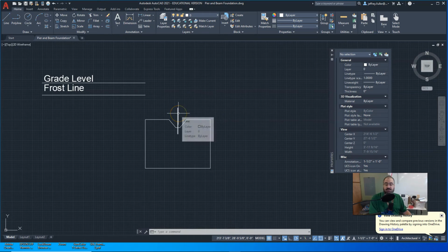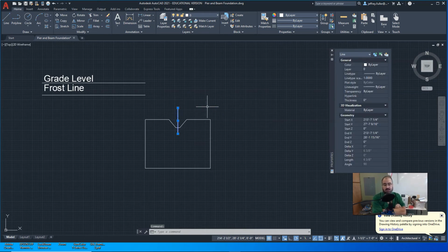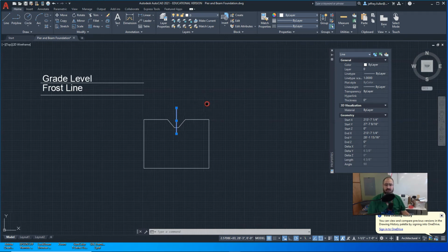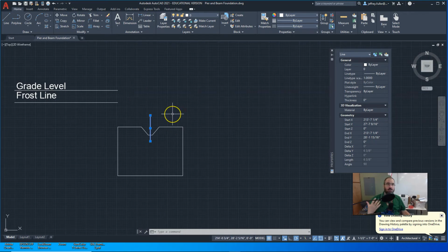Okay. Next, I am going to take this line and use this to make my stem walls, and to kind of locate those. Now my stem wall height is one of the things I have to look at. I'm thinking, okay, I'm going to make it 2 feet. There really is no exact designation about how tall the stem wall should be. You got to look at your crawl space underneath the house. So I think if I do it 2 feet, that's going to allow the 18 inches under the house or more. Now, of course, the 18-inch crawl space is just a minimum.